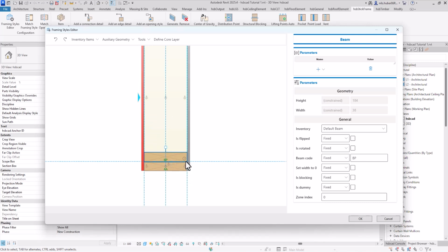And as you can see, here is an exclamation mark symbol. If you hover over this exclamation mark symbol, you get what's wrong with the beam. So this beam is not fully defined because we need to add more constraints. This means we need to activate these anchor symbols, and we need to activate 2 anchor symbols so that the beam is fully anchored into position. So, as you can see, the exclamation mark symbol is now gone, and I get a detail with no errors.